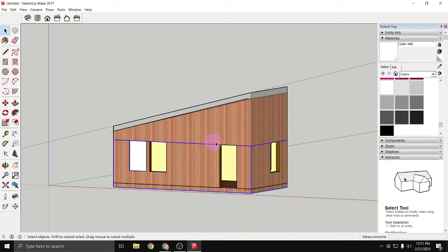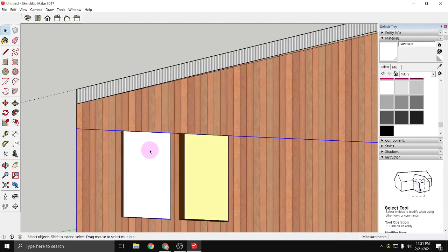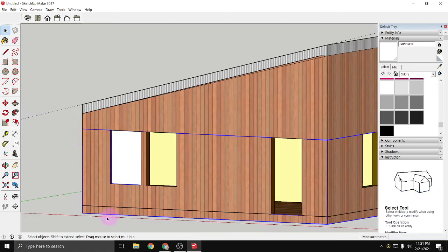The fact that this big blue bounding box for this window is going all the way around here should set off some alarm bells that, uh-oh, some things are in there that you didn't intend to. But I'll just Control Z to undo.